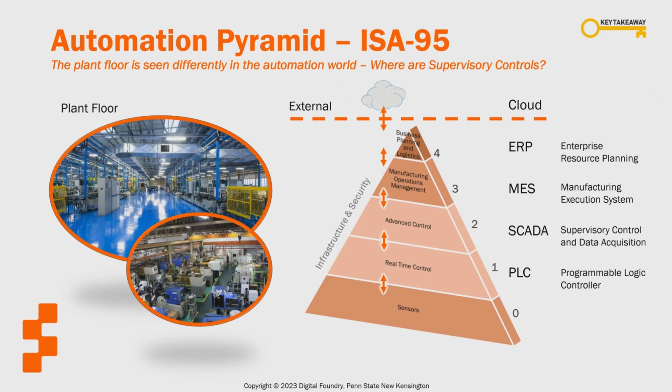Level 1 is the control or PLC layer, where PLC stands for Programmable Logic Controller. This is the level that is closest to your factory floor and where machine control resides. Level 2 is where you will find supervisory control and data acquisition systems, or SCADA, and human interfaces, or HMI. In this layer, process data is monitored through user interfaces and stored in databases. SCADA is typically used to control multiple machines and complex processes, including processes that involve multiple sites.